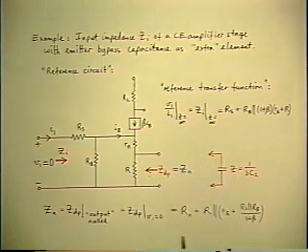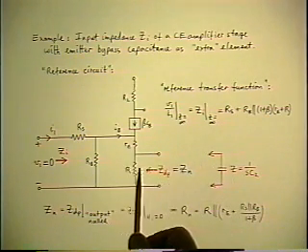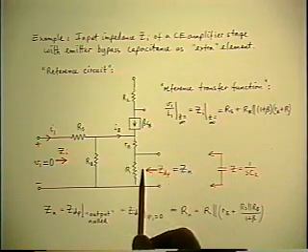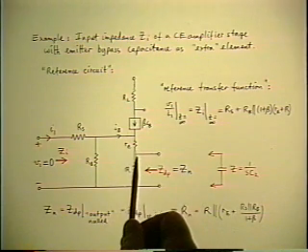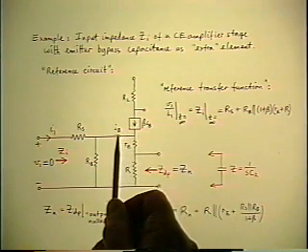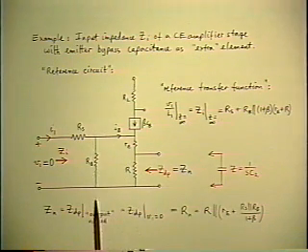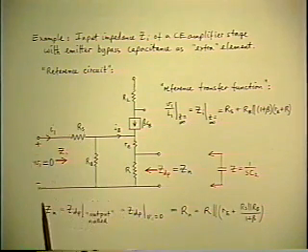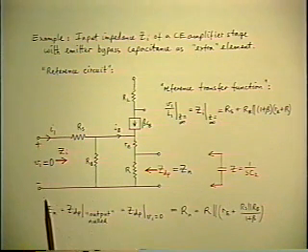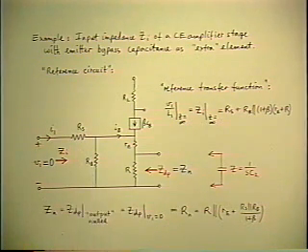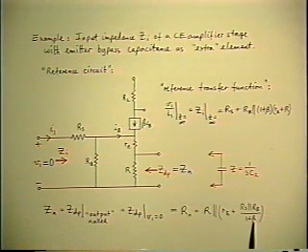And having established that condition, we ask, what is the resistance looking in? Which is R parallel RE plus the reflected base resistance, which consists of RB and RS in parallel. Because if V1 is nulled, it puts the RS back in parallel with the RB. So that's the answer for the Rn.